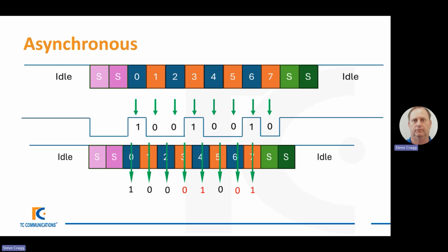The next one's a 0. That's good. The next one's a 0. That's good. Ooh, and then you can see that the next one is right on the cusp between a 0 and a 1. I'll give that a 0, and then a 1, and then a 0, and a 0, and a 1. So you can see, because the data was sent too slowly and was then sampled at the correct rate, or vice versa, that the data was sent at the right rate and was sampled too quickly, there's a slippage between these two, and that means that there are errors on the data.